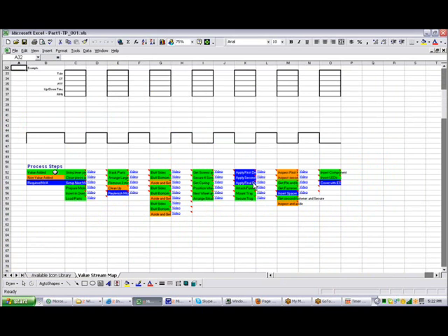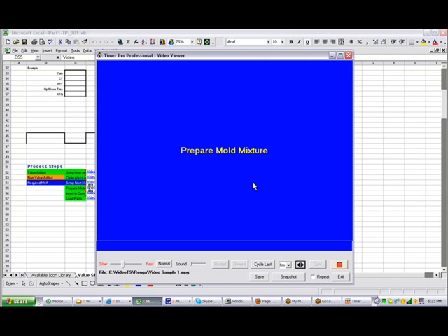And down here we've got a kind of unique feature to the Timer Pro package. Here are each of the steps in the process, along with the time. If I just point at the individual items, you'll see this is prepare mold, and it took 15 seconds to do that one. You can actually click here and see the video. So if I do a double click on the video field here, it will open up the free Timer Pro video viewer that you can give to anyone who's got Excel, and it will actually show you the video of that particular operation.